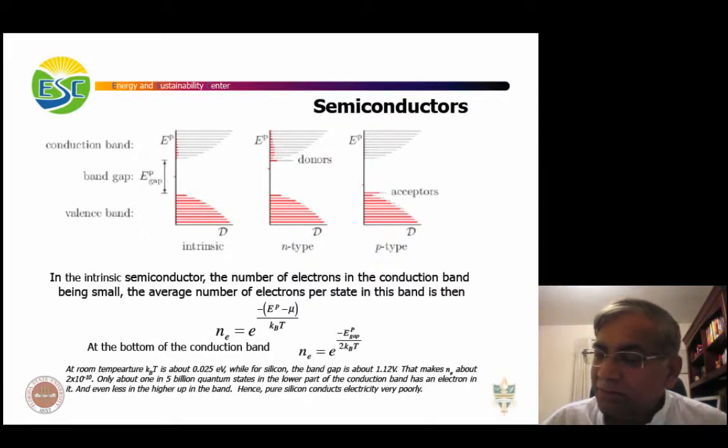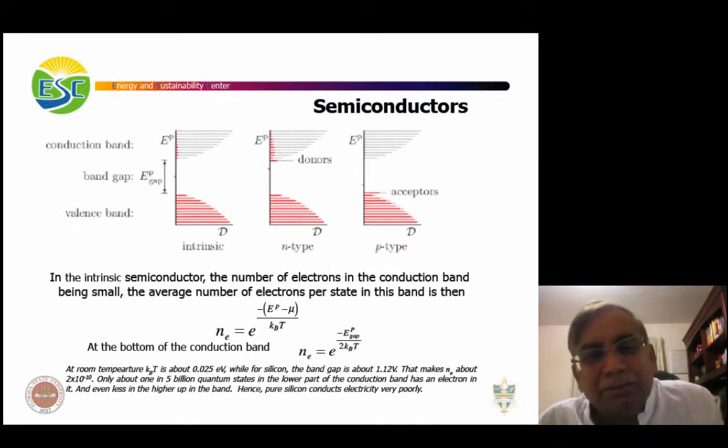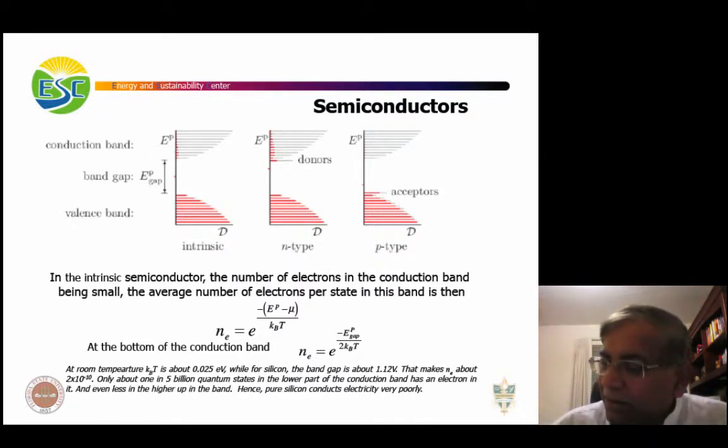That allows additional conduction to occur. Even at very small concentrations, such impurity atoms can make a huge difference, as we'll find out. For example, you can increase the conductivity of the silicon by a factor of 1,000 by replacing 1 in a million silicon atoms by an arsenic one in this particular case. So essentially what we do is we introduce here a stray atom, and that improves the conductivity of the semiconductor.